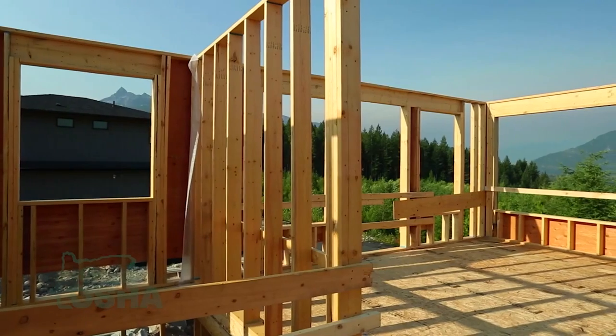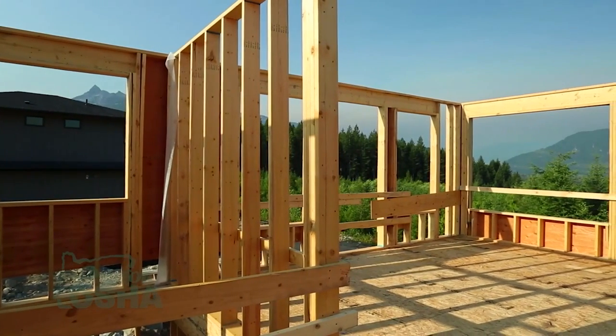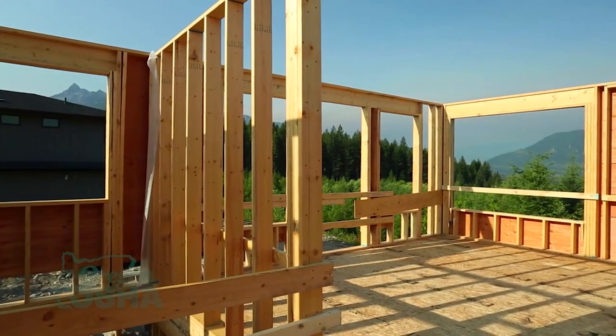So we need to start thinking out of the box when it comes to framing, and wood framing especially, on what our fall protection solutions could be. Some of the most common types of fall protection that framers can use to help keep their employees safe: I'm seeing a lot more guardrails being installed on walls before they're stood, so that as soon as they're stood, as they're framing that next floor in, they already have that guardrail in place. That's a lot quicker than setting up anchors in some cases, and it provides a really good visual barrier as well.